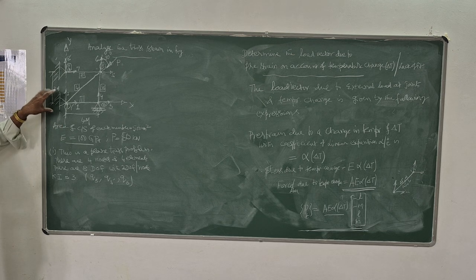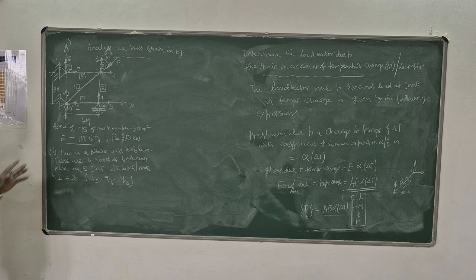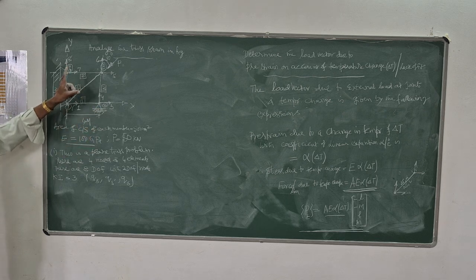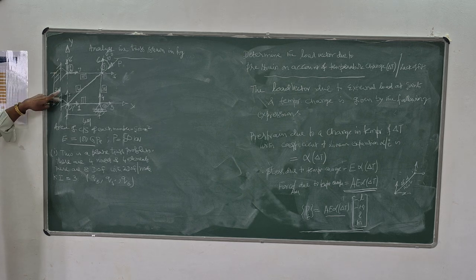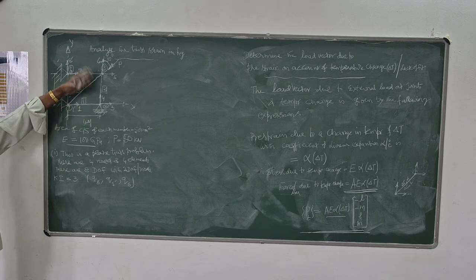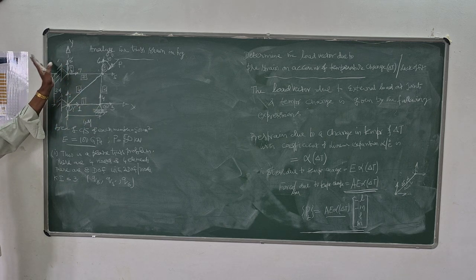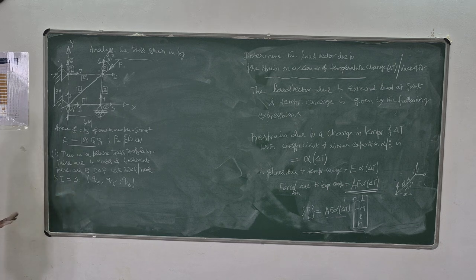Out of that, because of boundary conditions, some are restrained. Here 1, 2, 7, 8 and 4 are restrained. They are not possible because of boundary conditions, the two hinge supports and the roller support. The rest of the degrees of freedom we have to determine during our analysis.